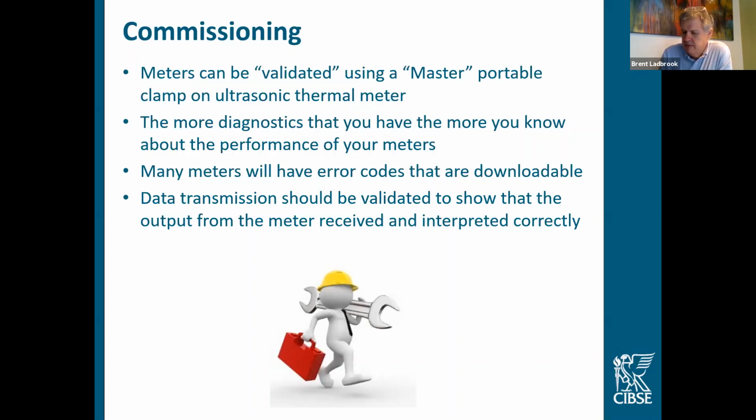My take is that if it's a meter that is certified and calibrated and it's installed in accordance with the manufacturer's recommendations and there's no error codes, I don't see a need to do this, and I've never seen any standard or best practice where it says that that should be carried out. Please let me know if you find it.